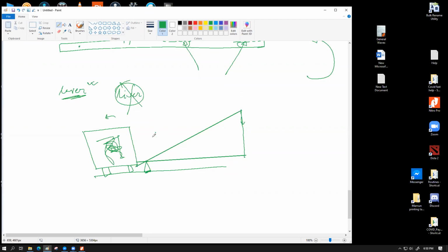So let's say we are going to rotate this rod by a moment of 10 Newton meter. I'm just assuming this number without any previous experiment. If it so happens that the length of the rod from the pivot all the way to this application point is, let's say, 10 meter, and if this much is only 1 meter, then to produce a 10 Newton meter clockwise moment along this line, we only have to apply 1 Newton force over here,